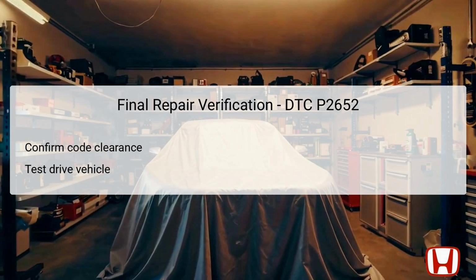After clearing the codes, conduct a test drive of the vehicle under normal driving conditions to monitor the engine performance and ensure that the VTEC system operates as expected. During the drive, pay attention to the behavior of the engine, particularly during acceleration when the VTEC system is supposed to activate. If the system responds correctly, without illuminating the check engine light again, you can confidently confirm that the